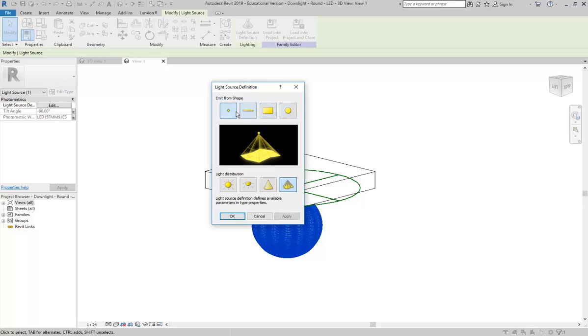So even though you've got those options, because they're not perfect, I'll show you in 3ds Max how you can make them work better. But that thing Rebecca was saying of copying the lights and having many lights along that linear path will give you a pretty similar effect. The problem with that is that the more lights you have for rendering, the slower the renders are going to go. And it's one of the main things that affects the rendering speed.